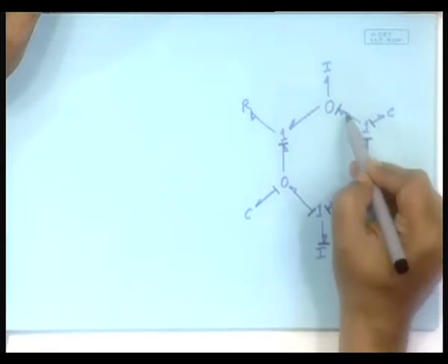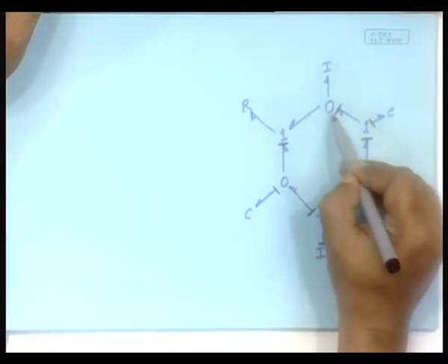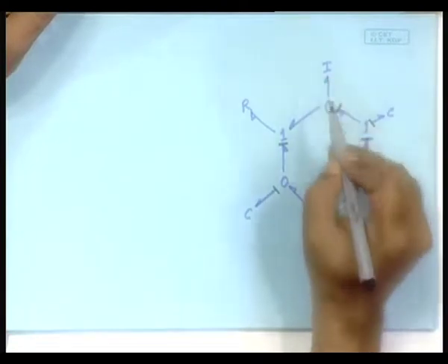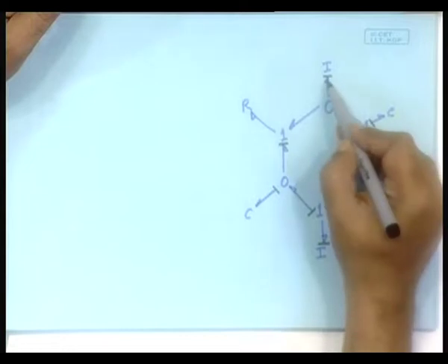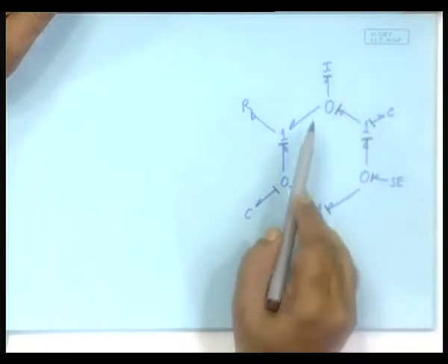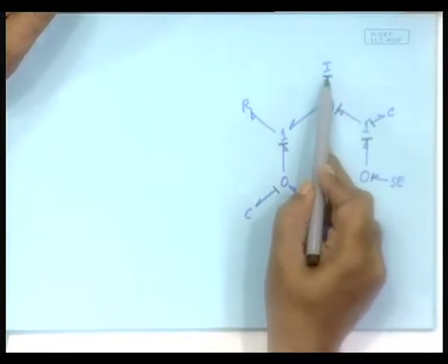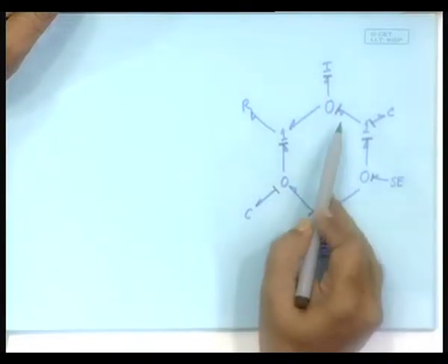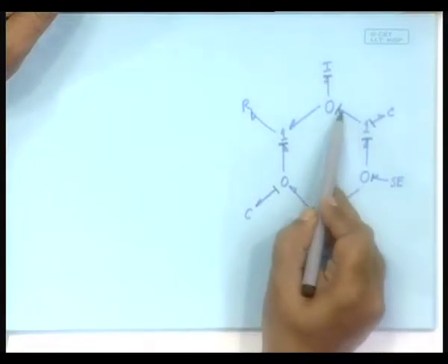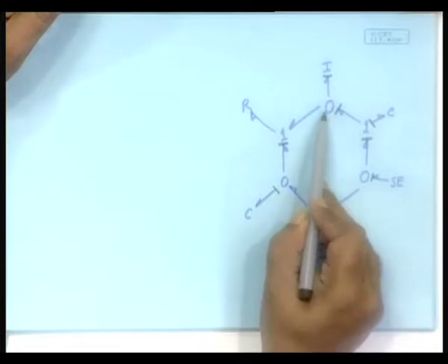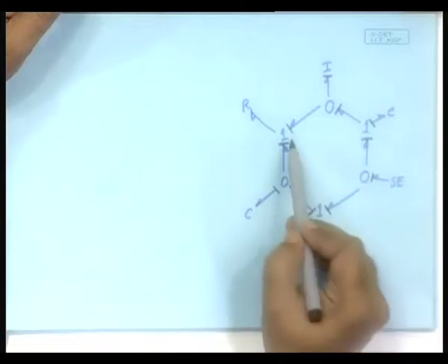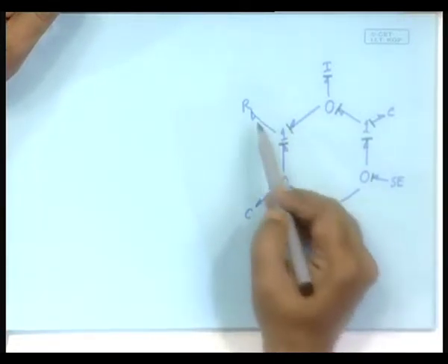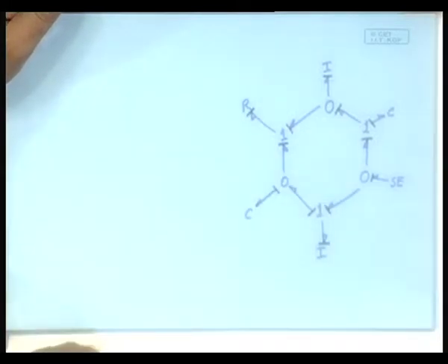So, in this 0 junction, as yet the causal structure is not complete. So, we will put it here. This is the natural causality of the I element. So, it has taken out the effort information, this one has brought in the effort information, 0 junction. So, this has to take out the effort information. 1 junction, both these are taking out the flow information, and therefore, this one must be giving the flow information.